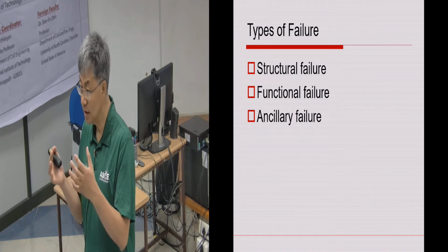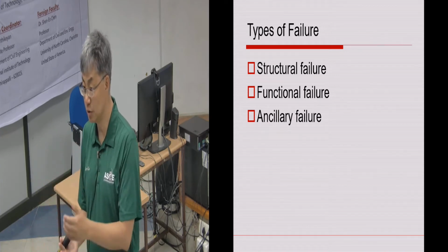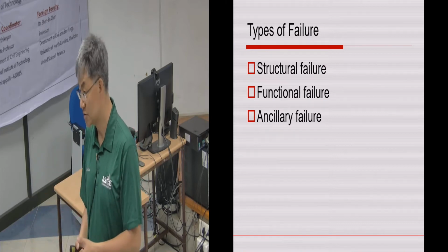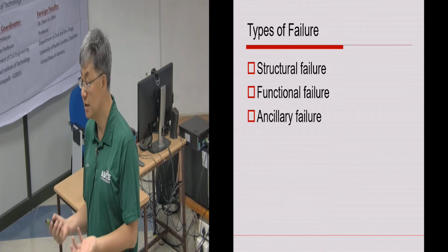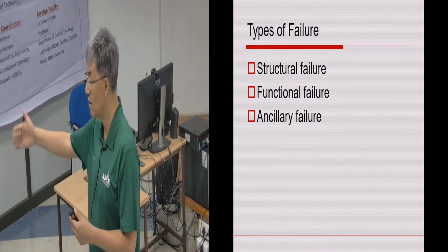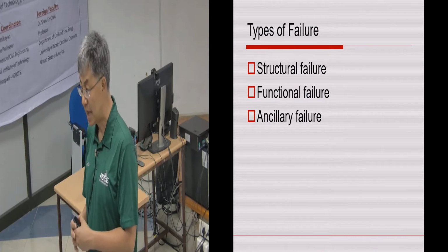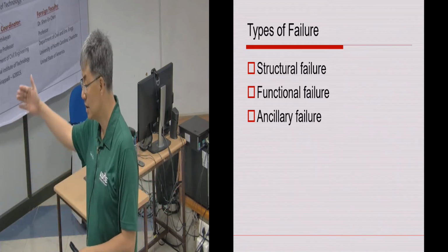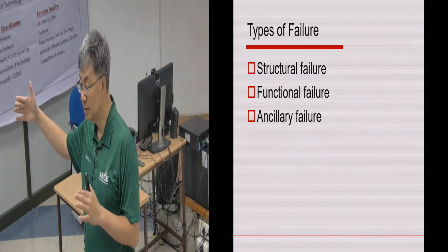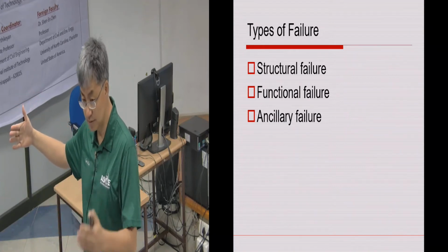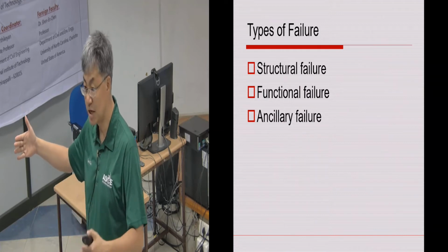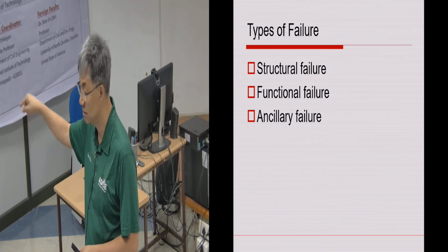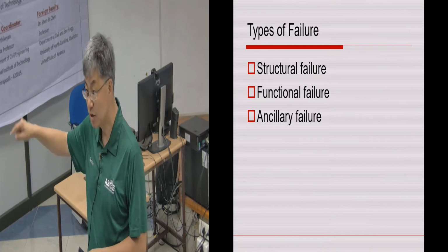Okay, and so this is where we believe that we need to have a curriculum specific for forensic engineering. And we're hoping that through the project you will be exposed to at least some level of that kind of expertise. An example I can show you would be if you have a building basement, and something happened. The basement will be underground, right? And there is a document on investigation and inspection technique that shows you that the crack pattern of your basement wall can tell you what happened.